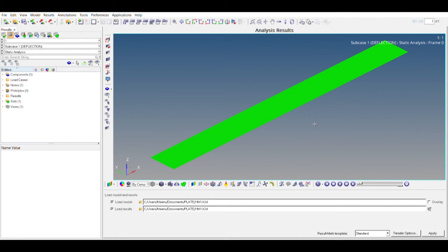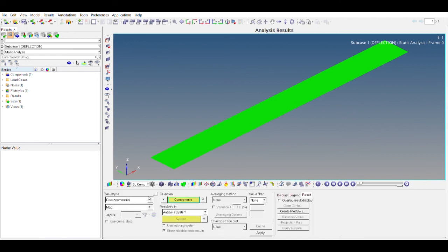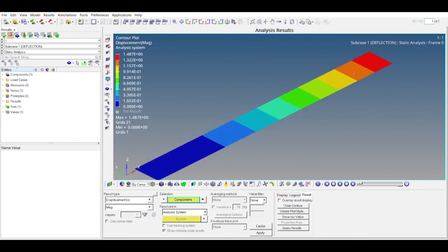Basically, it's a post-processor that shows the calculated results, a graphical, visual representation of them. For the visual representations, we'll go to contour. In the contour, we have options in the result type such as displacement or element displacements. We'll go for displacement and the magnitude, and select apply. While applying, we can see the red regions and blue regions in the contour plot.